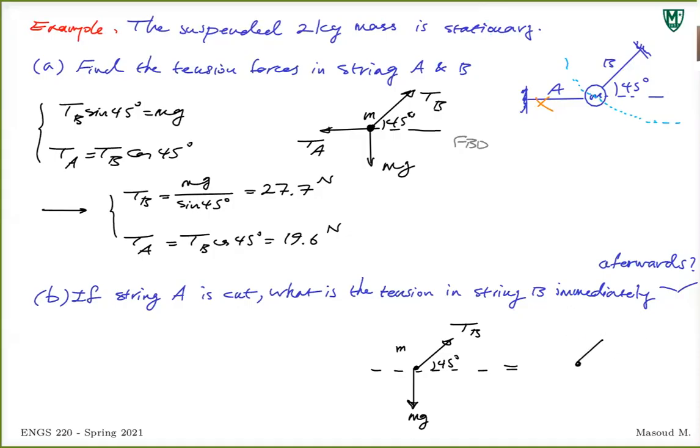Since it's a motion on a curvilinear path, now we can look at it like this: e tangent, e normal. So an object following a path, right? And that path is just a curvilinear path. So I'll draw it the way I see it. This is tangent, and this is normal on my kinetic diagram. This becomes m a tangent, m a normal.